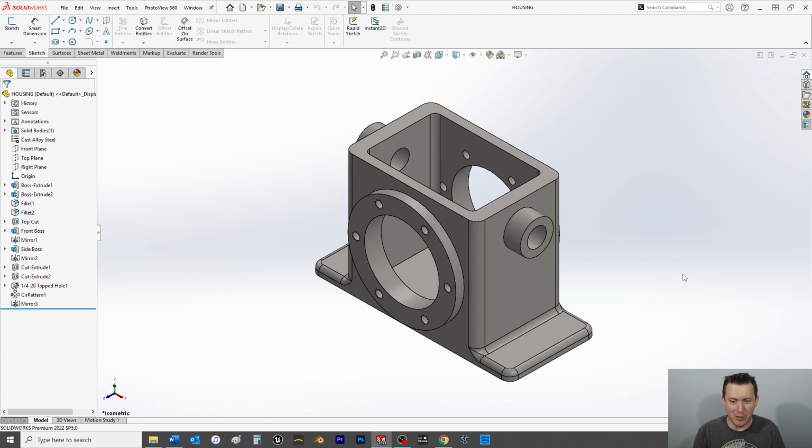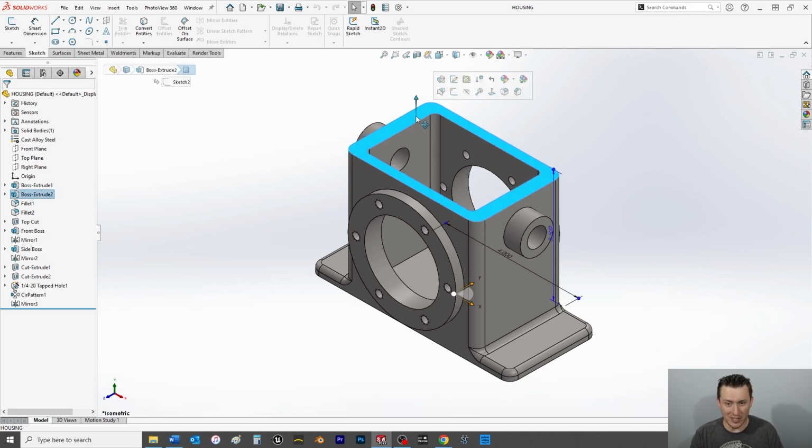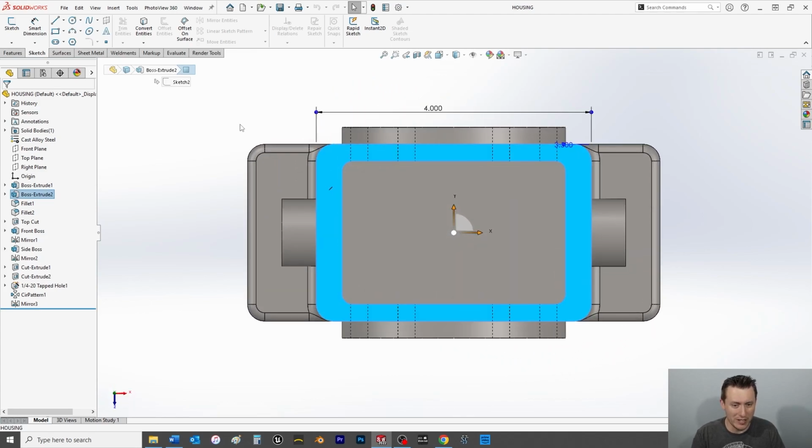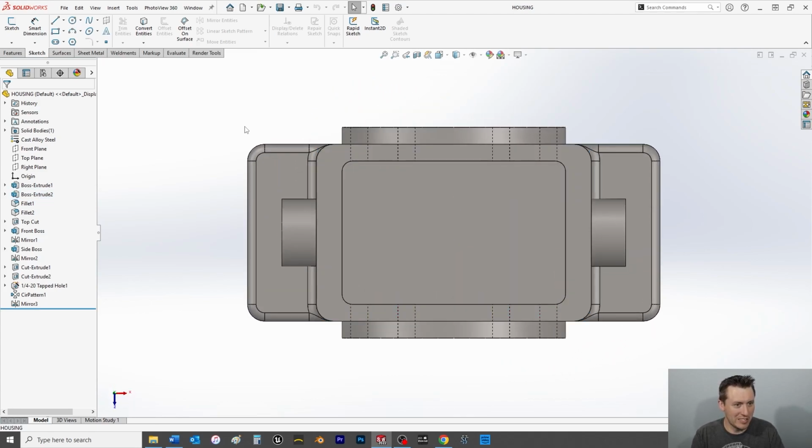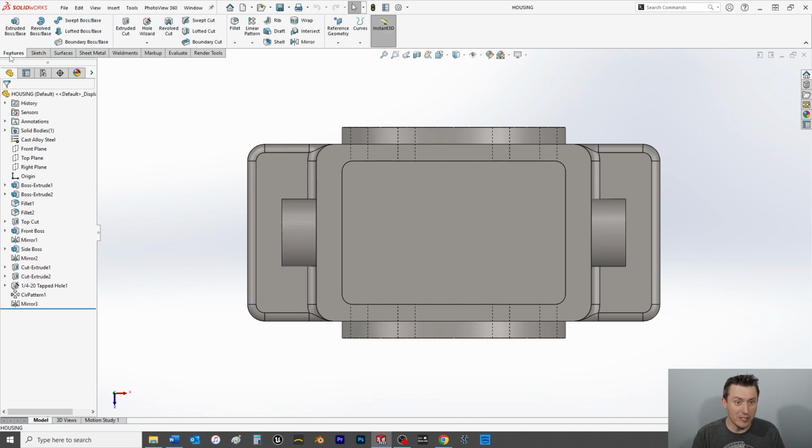For now, let's jump back into the model here. Page 90, section 2.54, we are going to add some number 6-32 threaded tap holes to the very top of our part. So let's begin. I'll select the face of the top of our part, press Ctrl A to bring it normal to. I'll hit Escape. And then I want to go to the Features tab up here on the top left and go back to our glorious Hole Wizard.